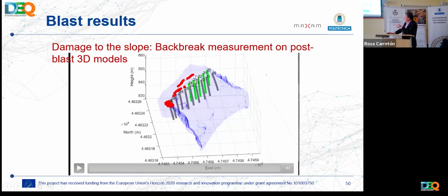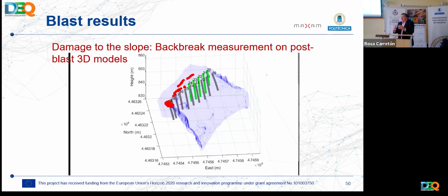Chances are that the displacement in the blast was not good. So when those holes detonated, they were highly confined, and then they did a lot of gassing out backwards, something like that. I'm not going to analyze that at this point. We would need all the information for that. Whereas here, back break is very, very close to where the holes were.